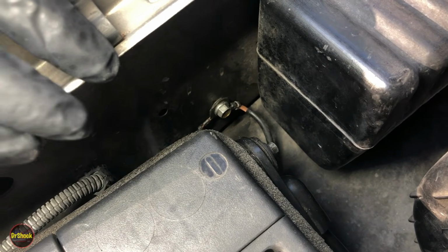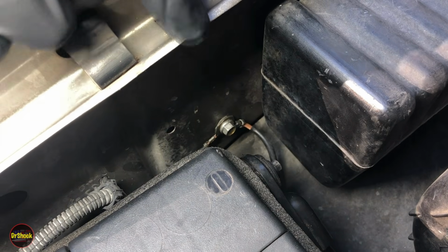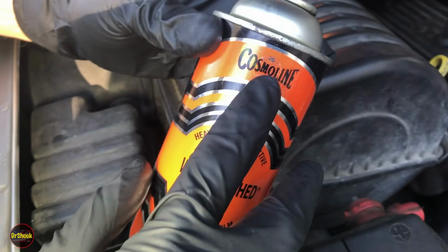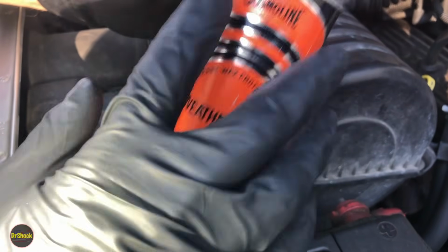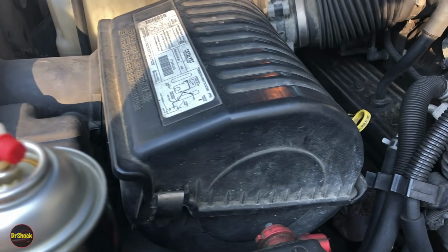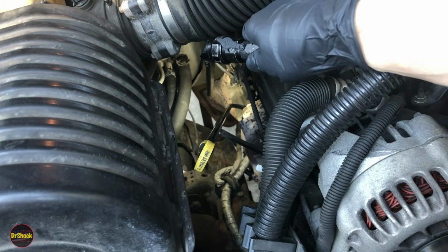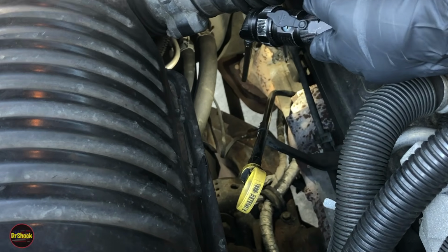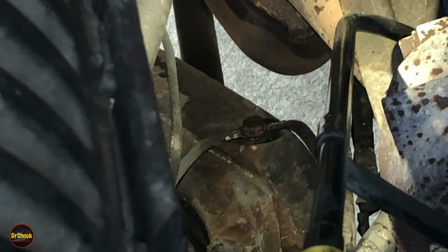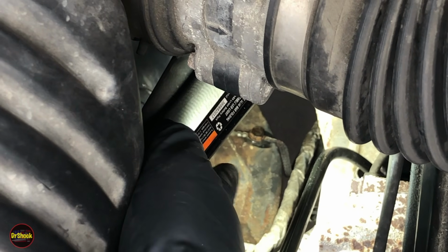So all I wanted to show you here, though, is since we've brushed off on this where the plating might be missing, what I like to put on these after I do that is something called Cosmoline. This is an older can, so the labeling might look different nowadays, but you just give a spray of this. So we sprayed that on here, and then also, let me grab the flashlight. Also on G104 back here, right down there. If we zoom in, we can see that we sprayed him up as well, just to seal up the work that we did.